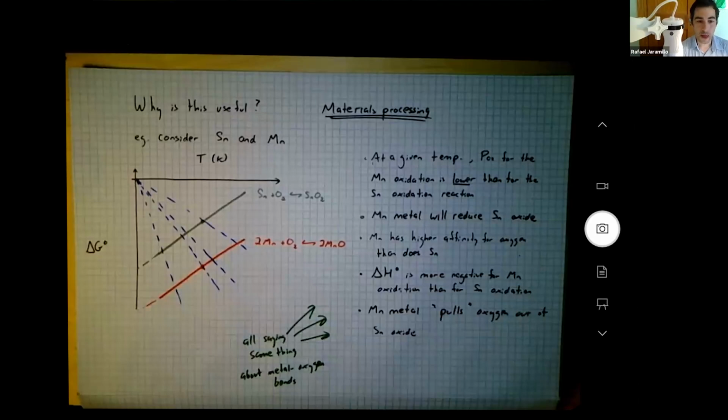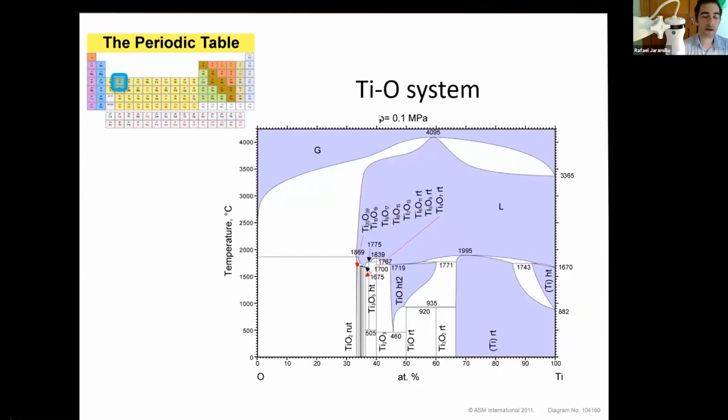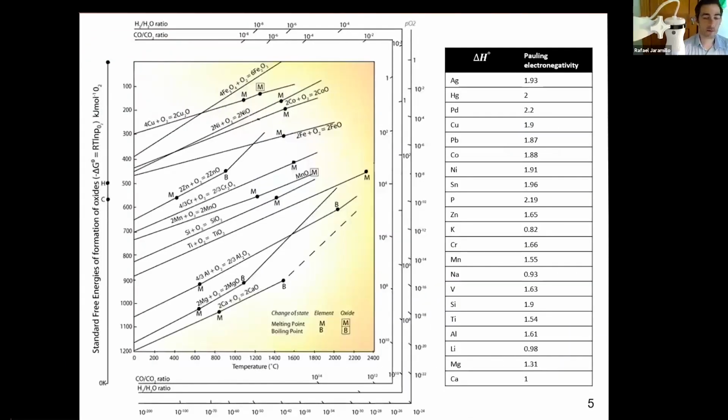Okay, I want to share with you some pictures of Ellingham diagrams. So there's lots of Ellingham diagrams out there. Here is one representation. This is a little busy, but you can see lots of things here. You can see many metals, which are all represented. Let me grab my laser pointer. Sometimes the laser pointer is stubborn. So here's iron oxidation reaction. Here's a nickel reaction, copper. As you move down, you're going to metals that have higher affinity for oxygen.